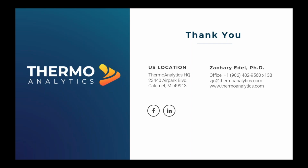The cells are discretized as shell elements in the model itself. The temperature is calculated on an element level basis. For the equivalent circuit models, the heat generation is applied on a cell basis. For the distributed model, that is also element level. But basically, it's just a thermal model with heat generated from an electrical equation that is based on test data.